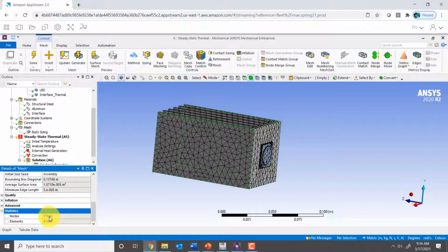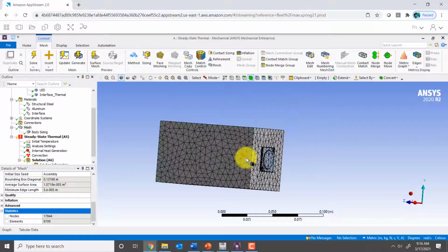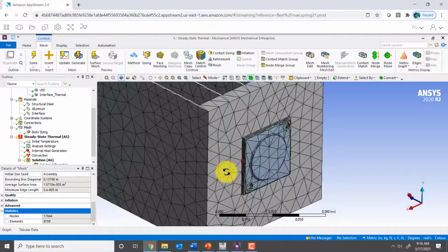by solving a system of algebraic equations. And you can go in here and highlight the nodes. So let's do that. If I go in and select the node selection filter, okay, I can control click, and I'll see that those are the points at which it's going to calculate the temperatures directly by solving a system of algebraic equations. And it also has mid-side nodes to get a second order interpolation. We won't get into that over here.